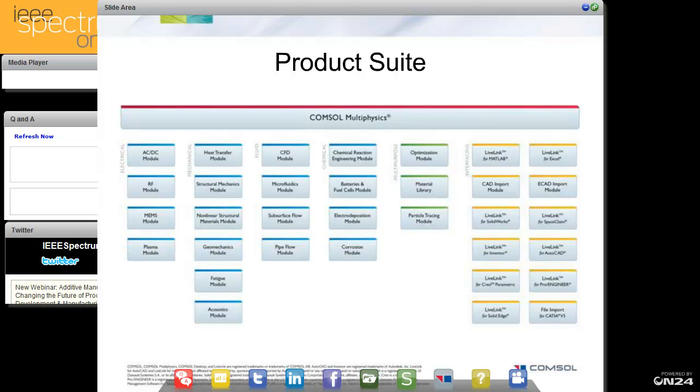But we have examples on how to do that as well. But I would say pretty much standard saturation effects are introduced by the use of empirical data, real magnetization curves that you specify using interpolation tables. And we ship some data for nonlinear materials as examples with the product, but it's very easy to import your own stuff from a text file or from an Excel file or wherever data source you have.